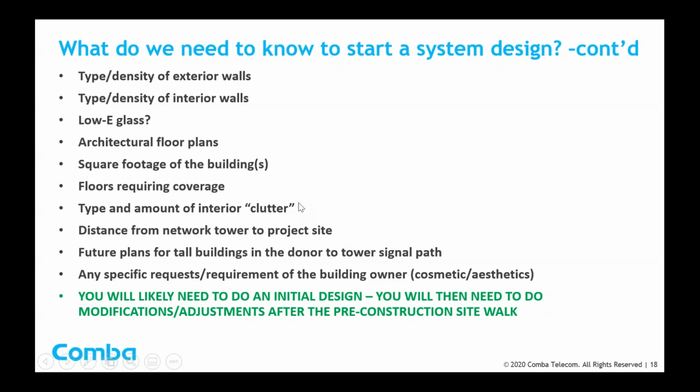People, office furniture, filing cabinets. In the case of a hospital, you've got a lot of medical equipment that can be a real clutter provider, and hospital medical equipment also generates a lot of spurious RF. So again, the DAS designer wants to know all these things. What's the distance from the network tower to the project site? Sometimes the building is, you know, half a mile from the tower. Sometimes the building is 15 miles from the tower. You need to know that.